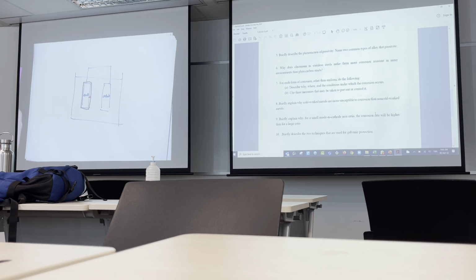If I coat the cathode instead and then scratch it, there's only one small little area demanding electrons over the whole surface area. You suck the thing out very fast, like a straw. So if you paint the cathode, the anode will not have a very localized attack even if it has a scratch. It will be more uniform. Does it make sense?